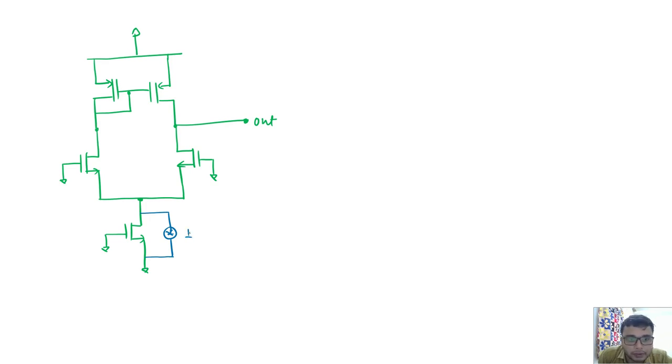But if I am considering the noise current due to M0 going downward, the direction is not that important because we usually consider the mean square values, the power terms. But if I consider one direction, we have to stick to that particular one only.